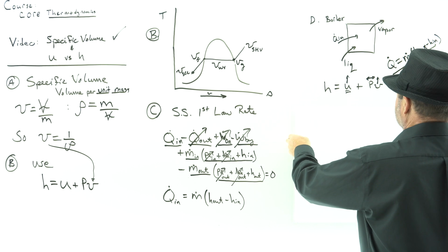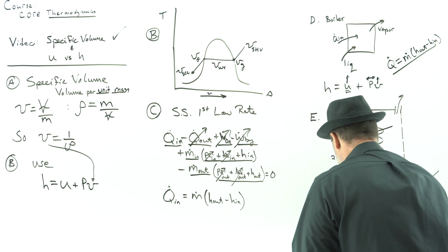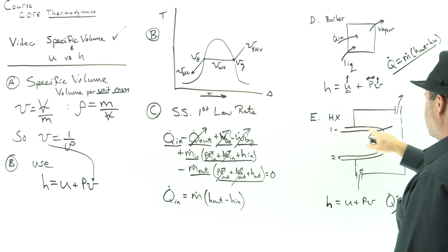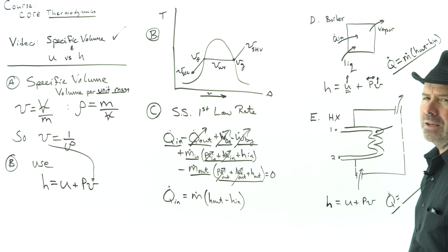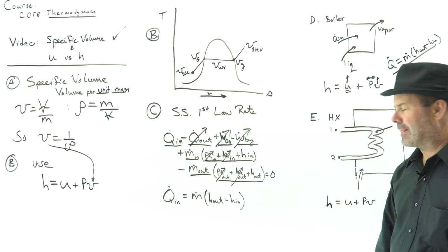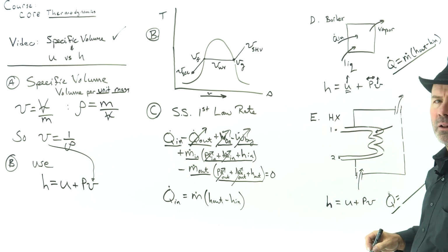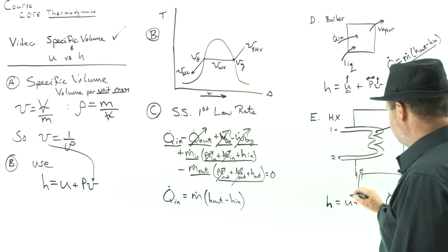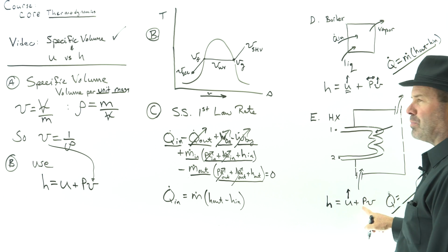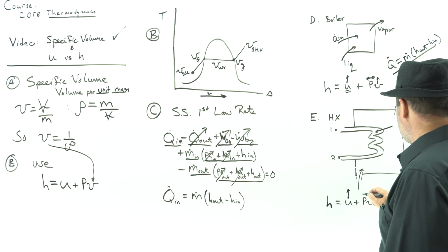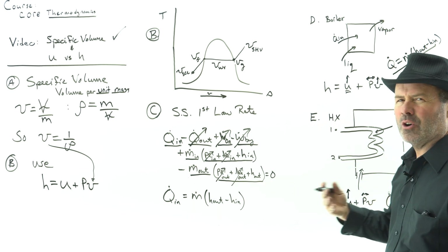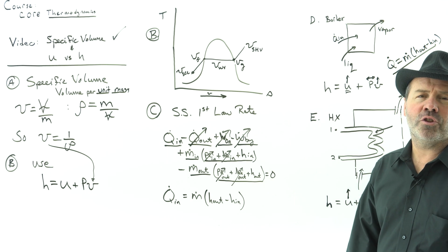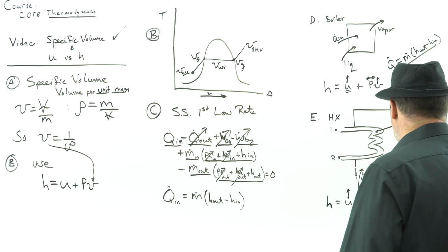Okay, well, let's contrast that. Let's have a heat exchanger where we're concerned with the fluid that's flowing through a pipe and not going through a phase change. It's just being heated up a little. Does its temperature go up? Yes. Does its pressure change much? No. Does the density or specific volume of a fluid change much over a temperature change with no phase change? And the answer is no, it really doesn't.